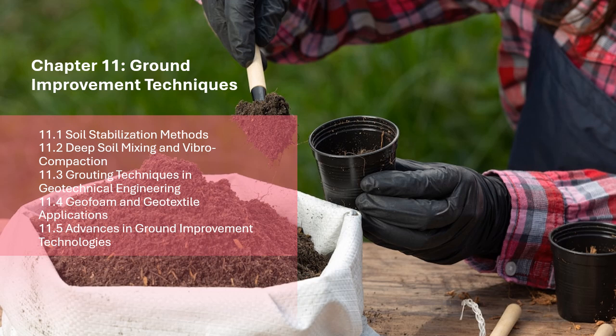Materials used: cement-based grouts, chemical grouts, e.g., sodium silicate, polyurethane. Applications: groundwater control, seepage prevention, foundation strengthening.